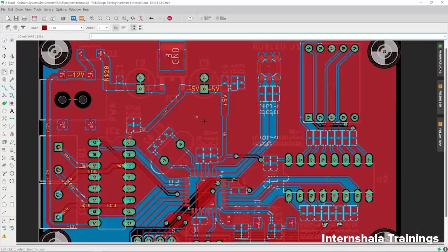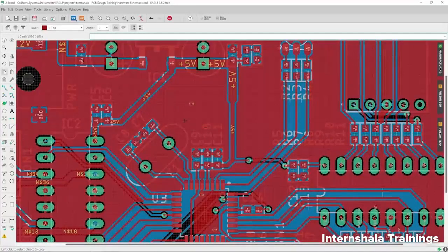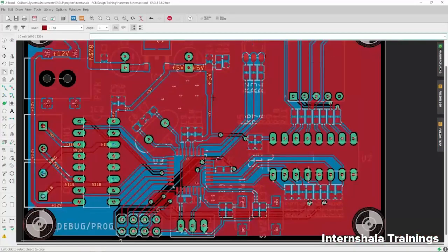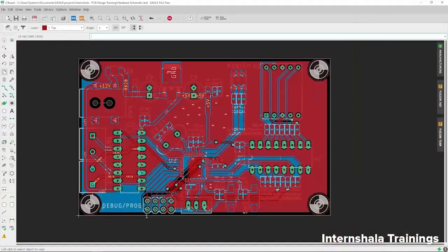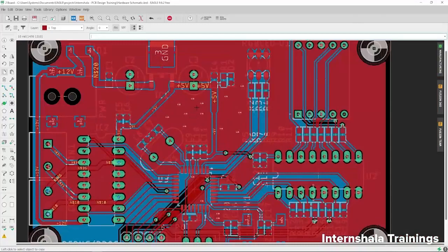But a single wire is actually enough in this application, but I will recommend you to place multiple wires like this, and you can connect in a proper manner, in a design also we can say, which I have placed in our layout. When I provide you with the final layout editor file, there you will get to know. So likewise you can place multiple wires, and this will resolve the issue related to the return path or return current path, and it's going to give a straight path towards the ground.